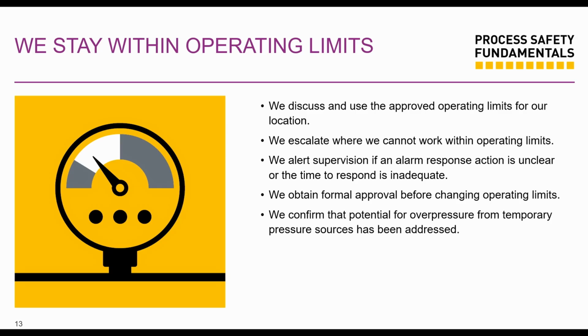You say, oh, yes, this is abnormal, but we have this every other week and it's becoming normal. No, we should respect the hazard, because your system was designed with an operating pressure and operating temperatures, and you are supposed to stay within those limits, because that's what your system is designed for.